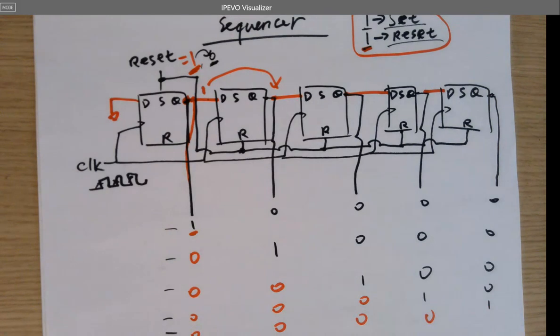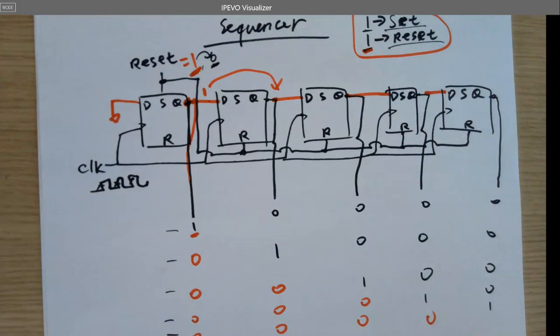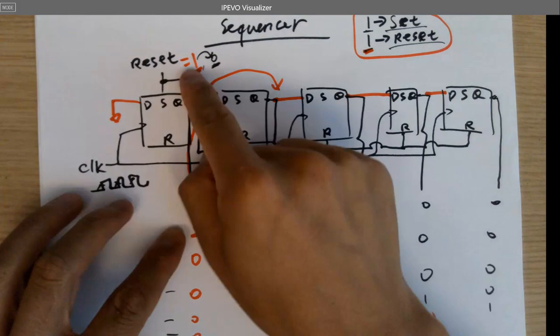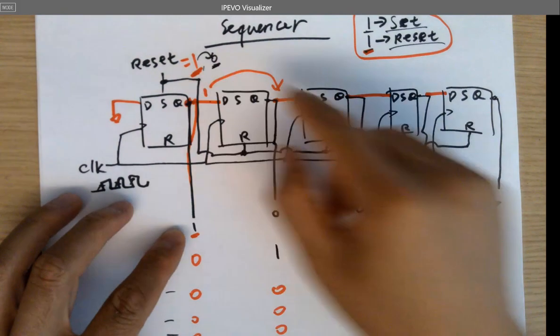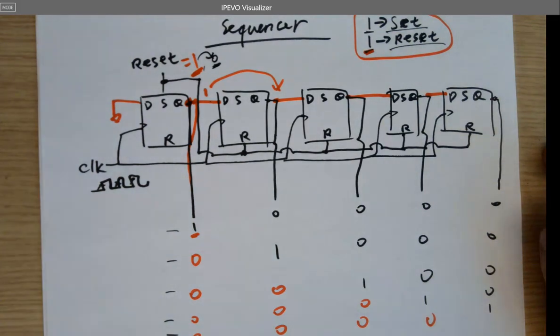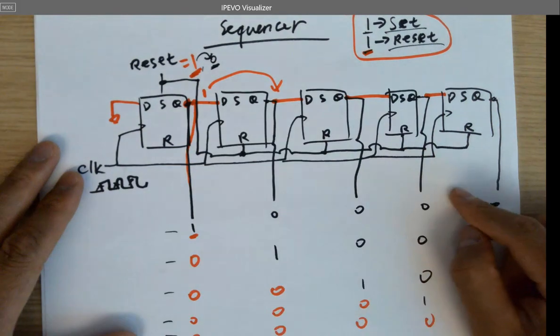No, you set it every number point being sampled, right? You sample and hold a DC there, right? Yeah. And then you reset it at the very beginning, and then put it to 0 for all the following steps of the conversion. And then whenever you want to convert another sampled analog data point, you reset it one more time, and then release it, and then do all the conversions.